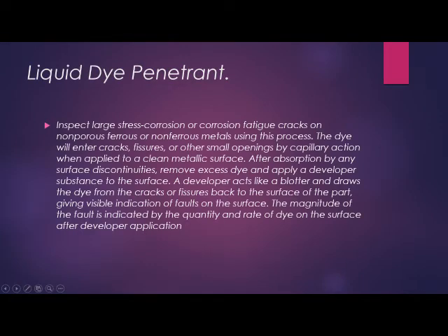First, liquid dye penetrant. Inspect large stress corrosion or corrosion fatigue cracks on non-porous ferrous or non-ferrous metals using this process. The dye will enter cracks, fissures, or other small openings by capillary action when applied to a clean metallic surface. After absorption by any surface discontinuity, remove excess dye and apply a developer substance to the surface.